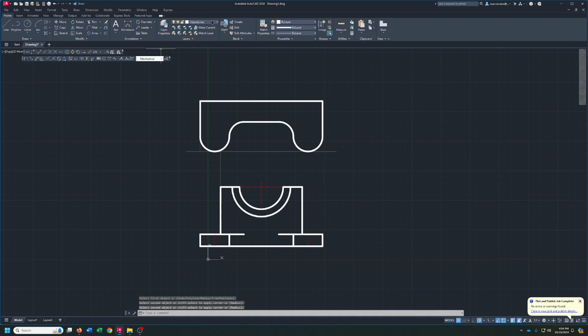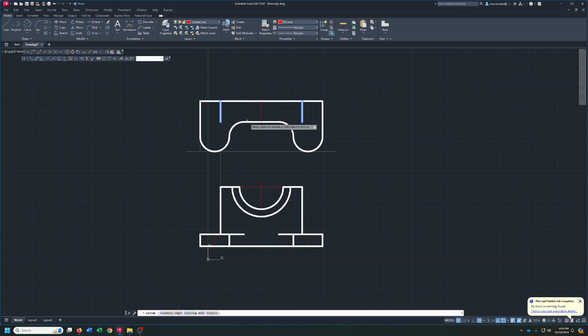And there we go. Now, I'm going to draw me a center line right through here. And I'm just going to stop right there. Now I'm going to offset that 3.5 both directions, because 3.5 is half of 7. So offset 3.5. One this way, one that way, and I'm going to change those two lines to the object layer. And then I'm going to extend one that way and one that way. All right, so that's got my top view almost done.